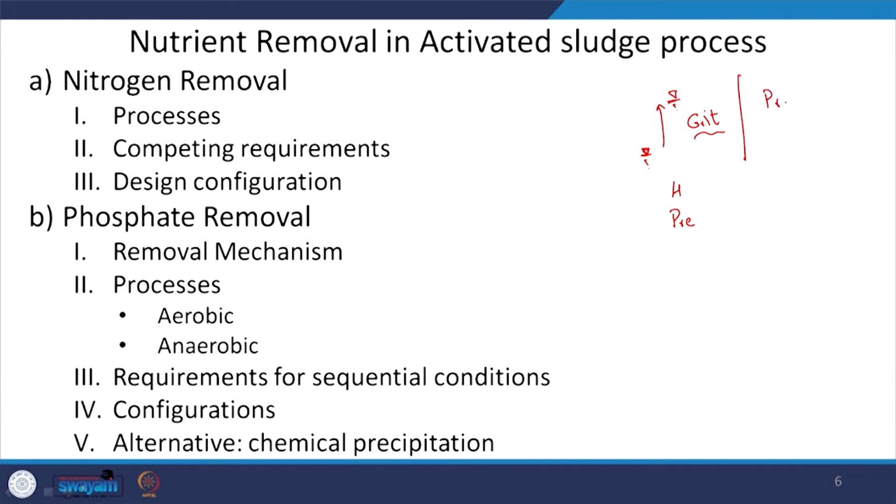And then in primary, again, this is optional in a wastewater treatment plant. It depends upon your priorities, because if you remove it here, you will have a lot of sludge which you need to deal with. So that is up to the relevant plant designer. Primary treatment, what am I trying to remove here? Primarily those compounds that are suspended in the water or wastewater, but which are heavy enough to be removed within a reasonable amount of time. So, mostly suspended matter and some BOD also, I think we mentioned around 30%.